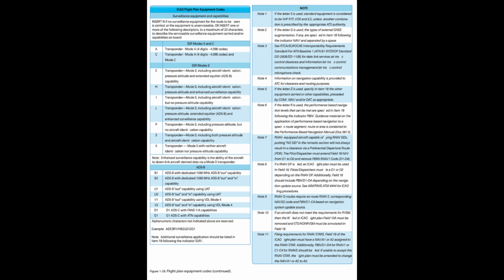In 2008, the FAA implemented the use of en route host automation ICAO flight plan (FP) processing for requesting assignment of RNAV SID, standard terminal arrivals (STARs), or RNAV routes in U.S. domestic airspace. This is part of a risk reduction strategy for introduction of the En Route Automation Modernization (ERAM) system in October 2008.